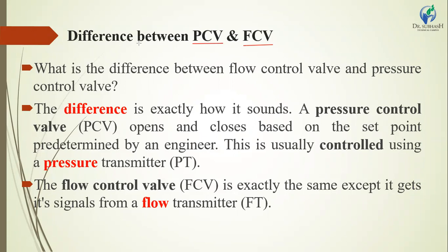All these types of valves control the pressure of the hydraulic system, and here the flow control valve controls the flow of liquid. If the flow rate of working fluid is more, then the cylinder will fill quickly, hence the piston will move faster. If the flow rate of the fluid is less, then the cylinder will fill slowly, and hence the piston moves slowly.